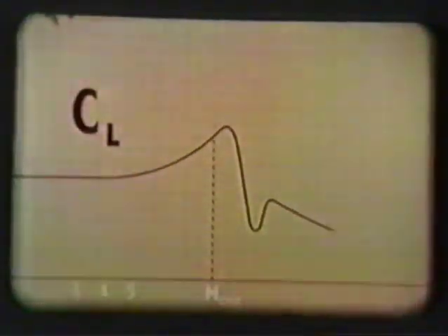This is because the air is becoming less dense as it speeds up over the curvature of the wing. But just above M crit, slow separation makes it plunge suddenly downwards. Later on, it increases slightly, then falls again.